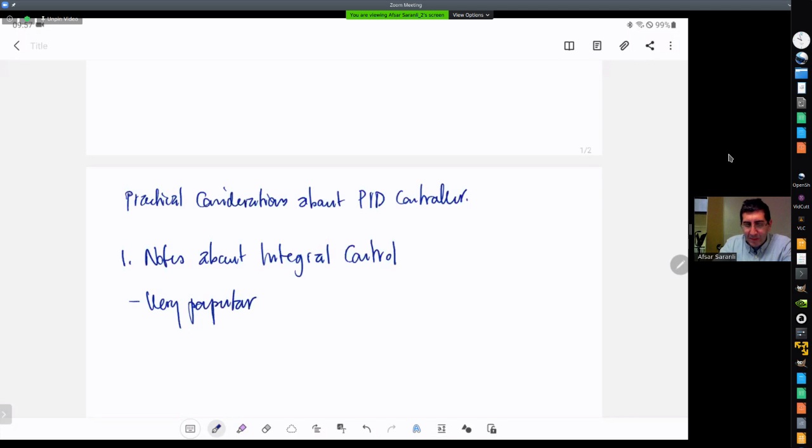But in PI control form, we discussed the reason for that. Integral control by itself, in fact, is not very desirable, although it makes the steady state error for a unit step response of a type 0 system go to 0. The presence of the integrator actually makes the system less stable. So it really narrows down the stable region. But when you introduce the proportional control as well, you basically make that slightly better, okay?